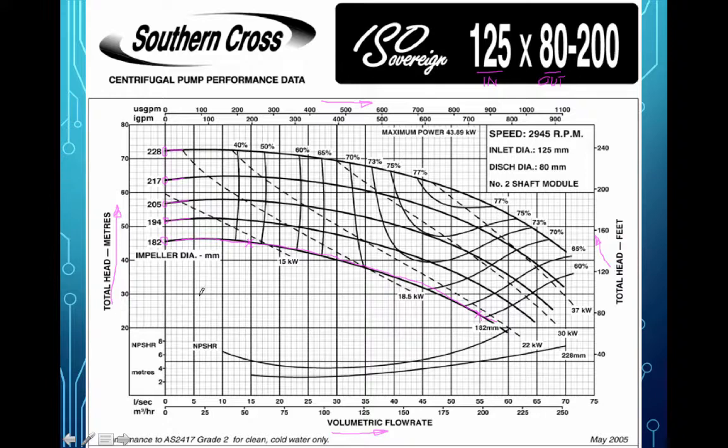So for instance, if we attach this pump to a vertical pipe and turn it on, that pump could hold up 45 meters or so of water in the vertical pipe. If we cut the pipe down to about 25 meters tall, it would have water come spitting out of it at a rate of 55 liters per second.